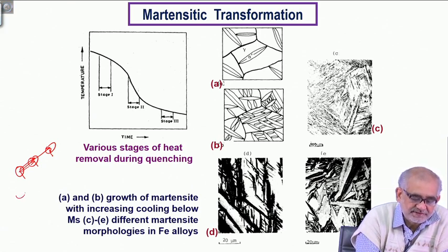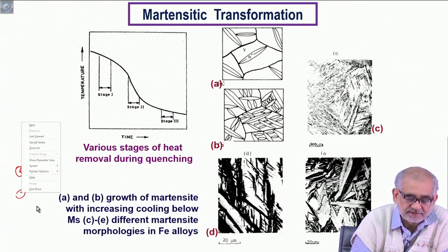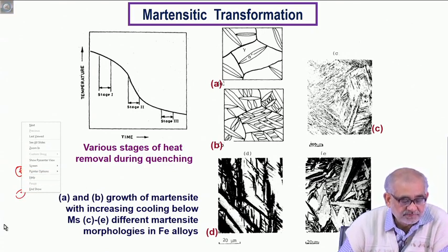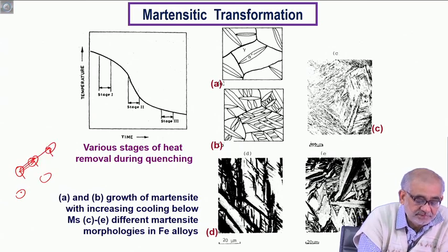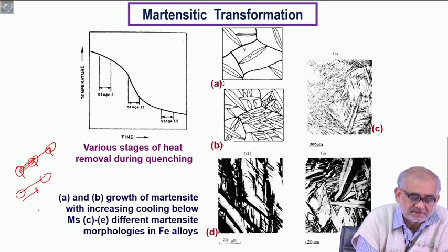When we talk of shear, then the two neighboring atoms, when there is a migration, the migration will not be exactly up to the next position of the atom. It will be rather somewhat in between. So the distance of separation will not be integral, but a fraction of interatomic distances.